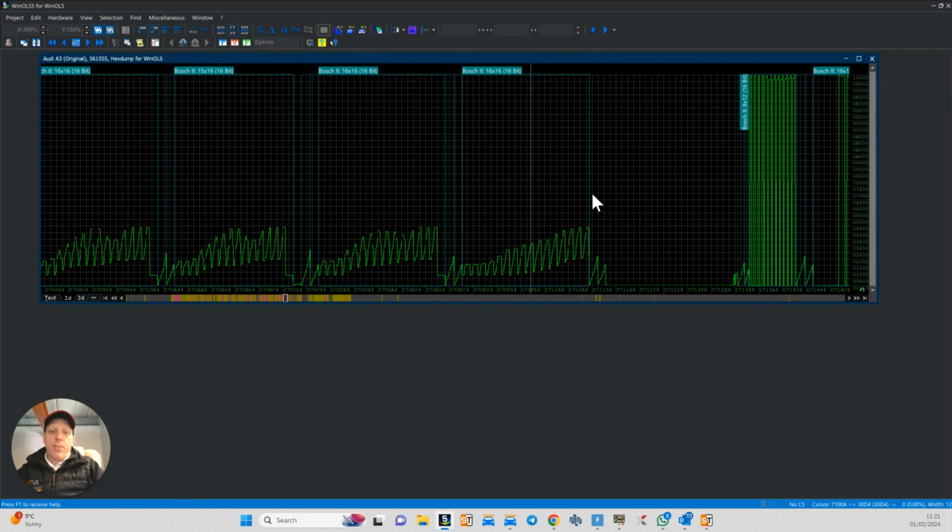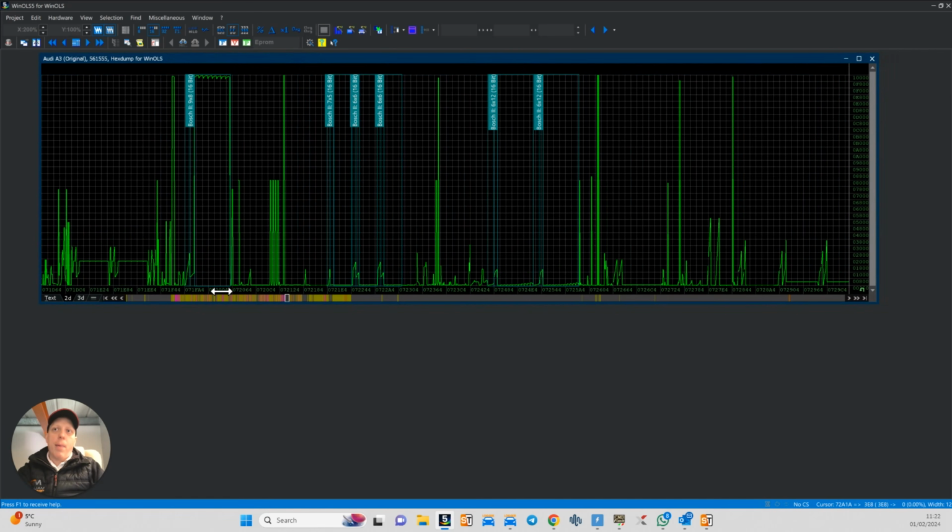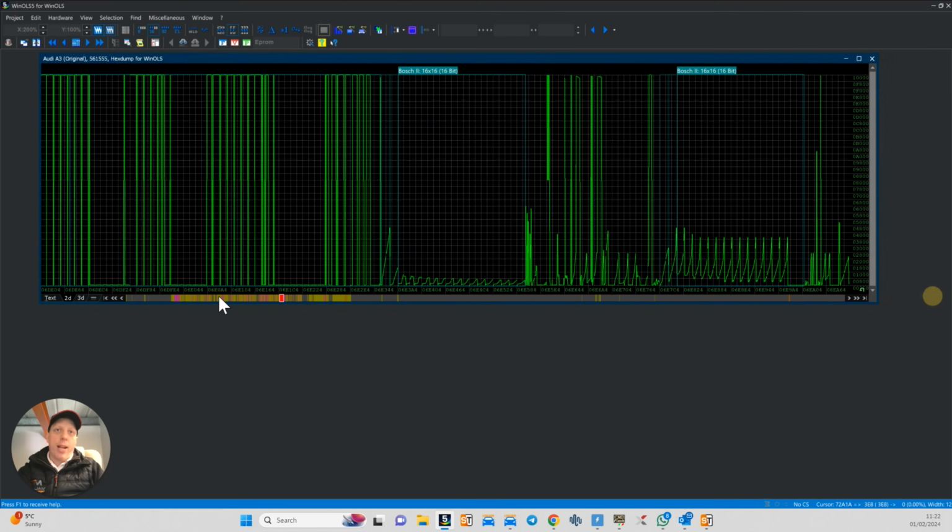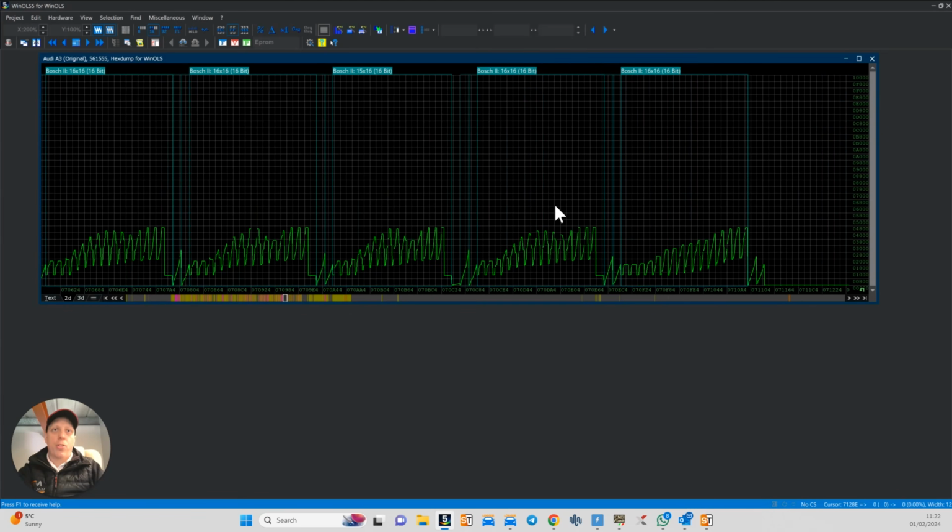So all these maps relate to something, and all these maps have got other maps that relate to them. So say you've got drivers, if you've got rail pressure, you're going to have rail pressure requests and all that kind of stuff. You've got different types of rail pressure based on different environments. So you could have a rail pressure based on height. You could have a rail pressure based on if you're in regen mode. You can have just a normal rail pressure, which is going to relate to a normal general driver when nothing else is going on, and it's all good.